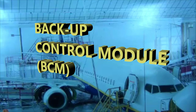You have a Prim1, Sec1, Prim2, Sec2, Prim3, Sec3, right? And those are supplying the power, or giving signals, information, data, whatever commands, to the intermediary components. For example, you've got your PCUs and any other transmission system to get over to the actuators so they can operate the control surfaces. So we have a backup control module and a backup power supply in case there's a failure of the computers.